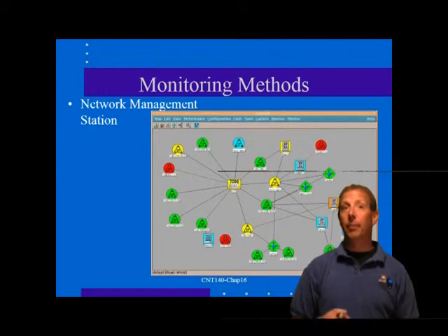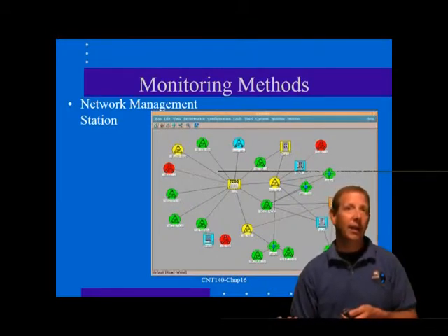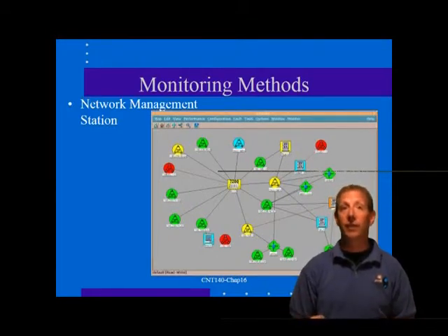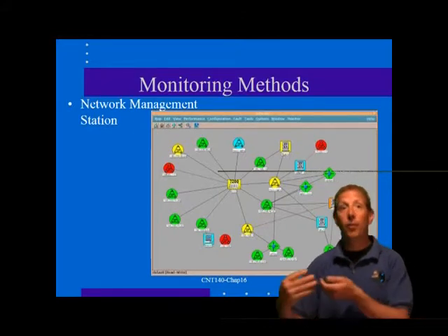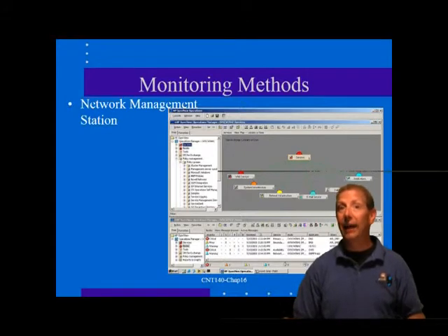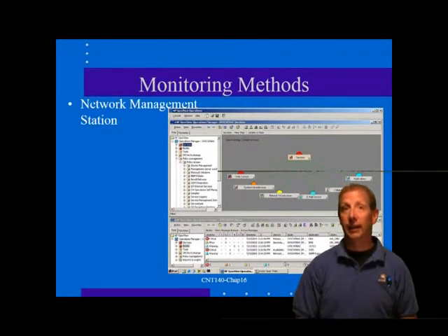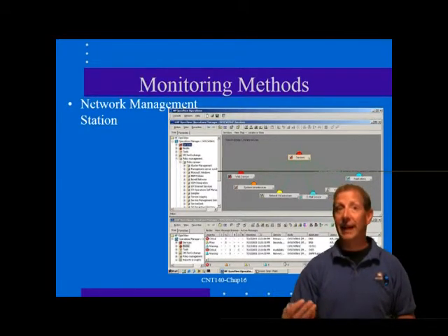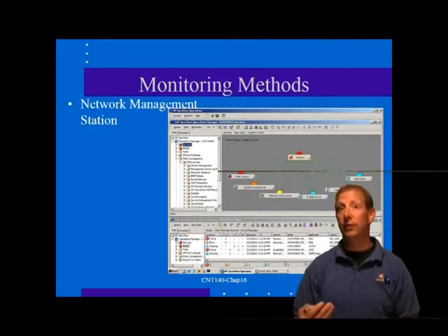These devices and their capabilities are specific to the type of LAN that you're using. All 10 Base-T, 100 Base-TX, and Gigabit Ethernet twisted pair systems provide a positive indication of link operation. A continuous link signal is built into the physical layer protocol. It indicates both link status and link speed. Standard 10/100/gig systems actually only evaluate the integrity of the received signal from the other end of the link. But enhanced systems can indicate integrity of the complete link, local and remote, and report the link status to a remote monitoring system.